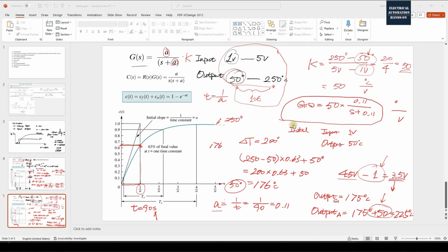Another important topic is the initial status. So most of the people, while they are using the transfer function to represent their system, if they ignore the k, ignore the gain calculation, or calculate this wrong, or ignore the initial status, or didn't record correctly this initial status, then your transfer function cannot fully represent your process system. Then you cannot do any of the rest of the calculation anymore. Okay, this needs to be done very carefully.